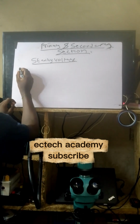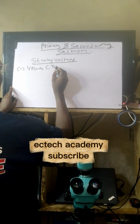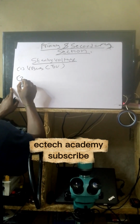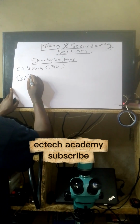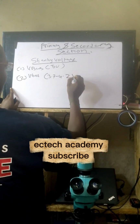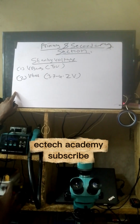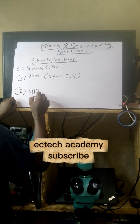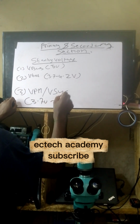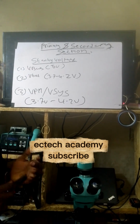So what are the standby voltages? Number 1, VBUS, which is 5 volts. That's the voltage coming from your charger. Number 2, this is VBAT, 3.7 to 4.2 volts. That's the voltage coming from the charger IC to charge the battery. Number 3, that's VPH or VSYS, also 3.7 volts to 4.2 volts. This is the voltage that will go to all the mobile PCB sections.